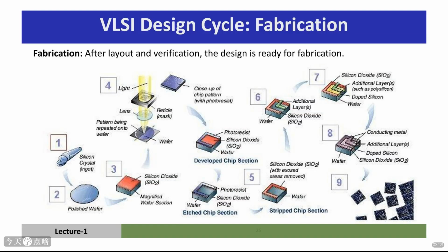Once the physical design is complete and verified, it's time for fabrication. This is where the magic happens in the cleanroom facilities of semiconductor fabs. The layout data, often sent on a tape, triggers the creation of photolithographic masks. These masks are like stencils, defining the patterns for each layer of the chip.